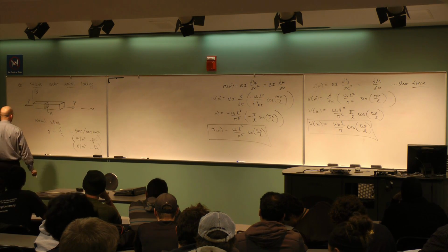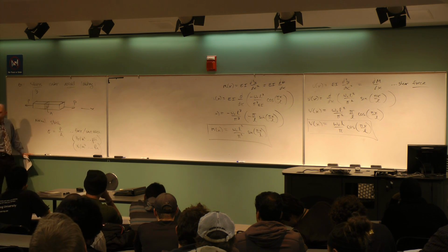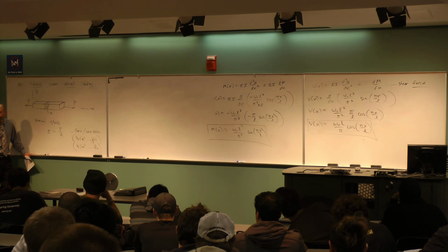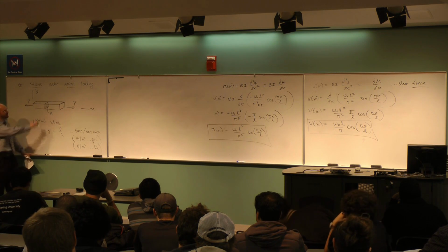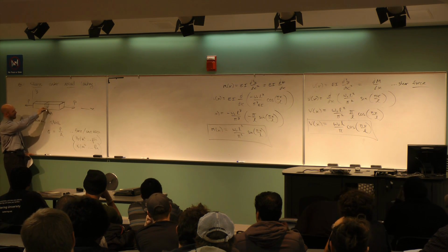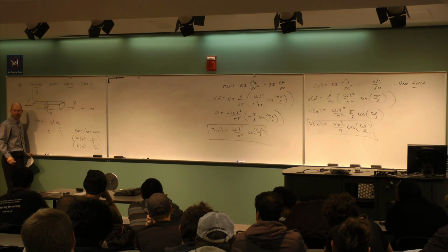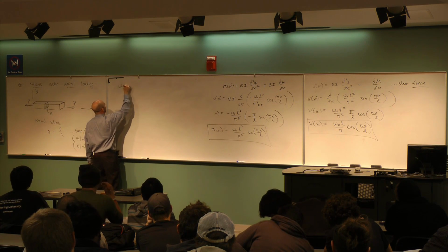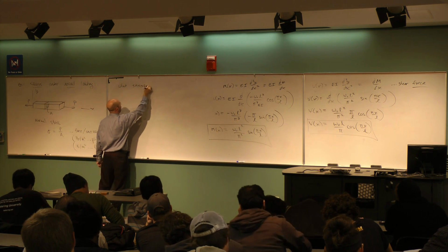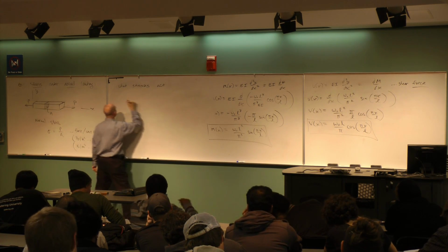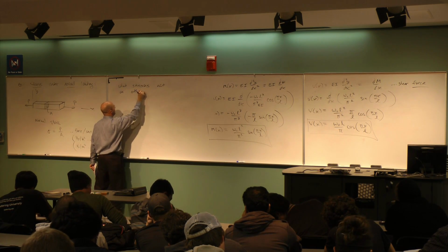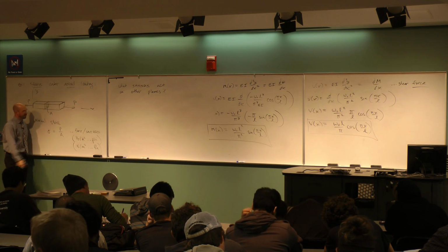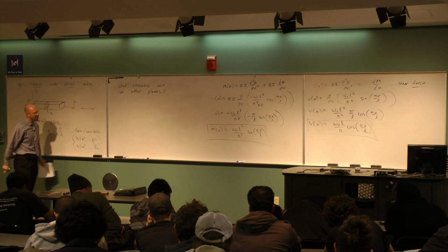And so if I start trying to define whether or not this breaks based on my made up coordinate system, how do I know that what I'm even doing here is the worst thing that I'm doing to the material? I could look at it normal this way. What if I looked at it at some other angle? For example, what stresses act on other planes in here? I drew one plane and I defined the stress, P over A. Great, that seems like it's got the right characteristics.